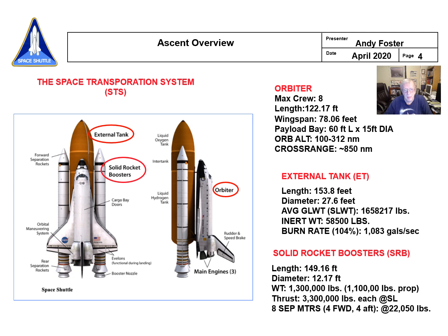And then, of course, helping that, the engines alone couldn't have gotten it to orbit. We had 2 big solid rocket boosters, 150 feet long, 12 feet in diameter, each one putting out about 3.3 million pounds of thrust. And each main engine put out roughly about 470,000 pounds of thrust. On the solid rocket motors, there were 4 separation motors at the top and 4 at the bottom that helped pull them away from the tank once you decided you needed to jettison them.